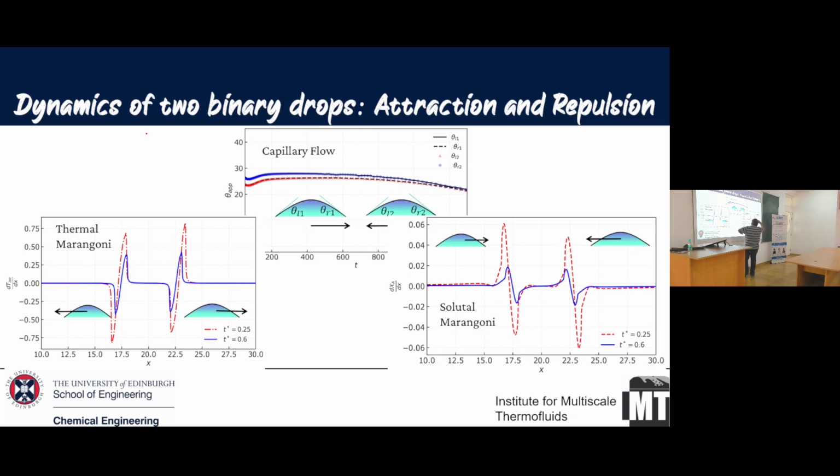Okay, so whenever you have a solutal Marangoni effect, when it is stronger, you have basically attraction. So if you increase the temperature of a substrate, you will ultimately drive these things far away from each other. But then if you want to defeat that, you increase your solutal Marangoni and they're going to come together. So you can actually manage coalescence or segregation of droplets based on this.